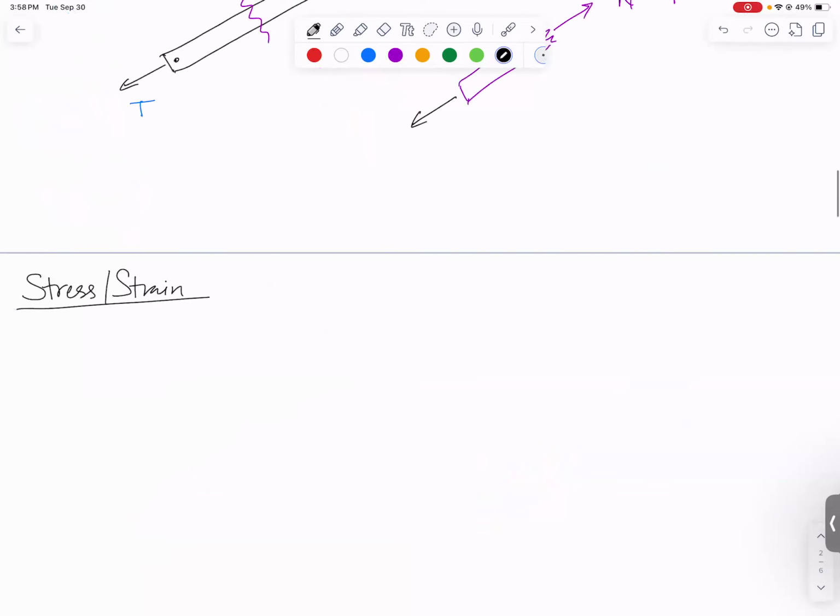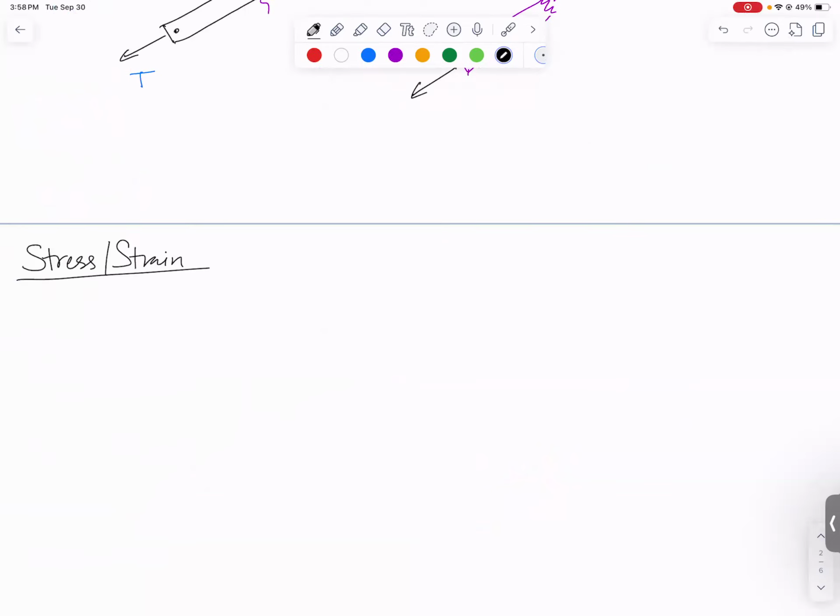All right, moving right along to stress and strain. Let me remind you of the definitions. We had normal stress, which was Greek letter sigma, equal to normal force over area. And the picture we have for that is, here's my area right here. And the normal force, it is an internal normal force, acts in that direction, perpendicular to the cut or along the length of the axis is another way to think of it.